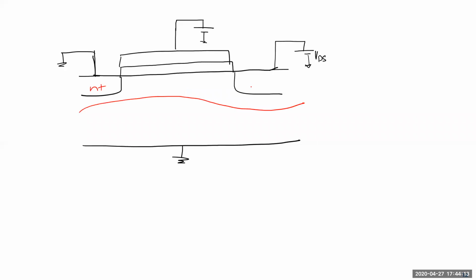I like what I think Puneet is saying. What I understood is that VG is constant. Once the depletion charge increases, phi s will decrease, and the oxide voltage, V ox, will remain the same, but phi s will decrease. So that's why you need to increase the gate voltage to get it back to wherever you want.